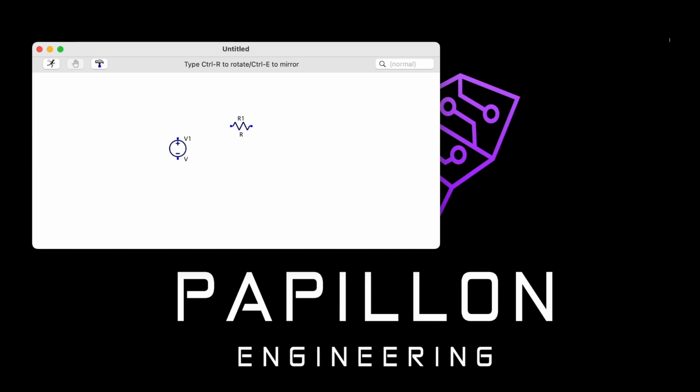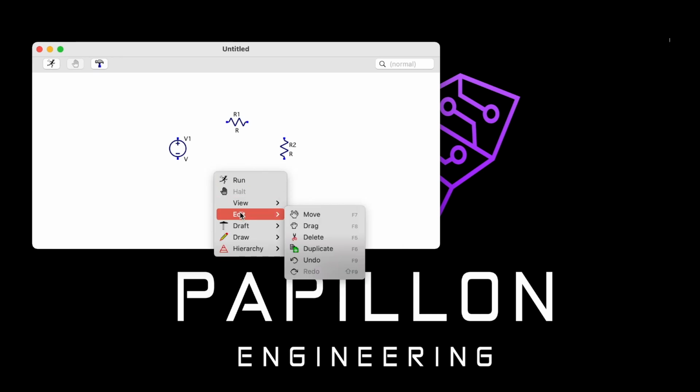As you can see here, it says press Control R to rotate any of your components. So I'm going to put down 3 resistors, hitting Control R to rotate them. I'm arranging the series circuit into a nice, comfortable pattern that I can work with. Once you have the arrangement, we have a series circuit with 3 resistors and 1 source. You hit escape to break out of it.